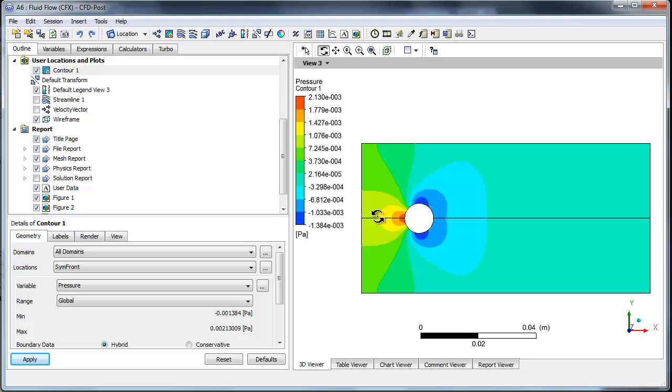I would expect pressure decrease as the fluid has to accelerate as it travels around the cylinder. The lowest pressure region is right before flow separation. Flow can't turn the corner anymore, and then I have a lower pressure region behind in the wake. And I can see that these things have, I've given them sufficient distance to work themselves out. I have lower gradients in those regions.